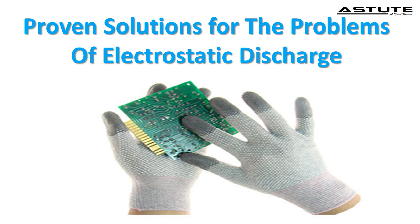Make sure the grounding system for equipment has low impedance for ESD currents to dissipate to an earthing reference. Use a metal oxide varistor, MOV, to protect the circuit from ESD. Use a transient voltage suppression TVS diode to bypass the ESD to ground.